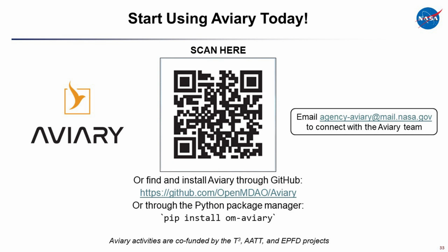Yeah, great question. So the workflow that AATT used for this aircraft is they used both VSP and VSP Aero. They used VSP as a way to define the geometry for the TTBW, kind of parametrically as they vary things, getting more accurate estimates for surface area and things like that as they change like wing chord, things like that. So that's how they hooked it into the model.